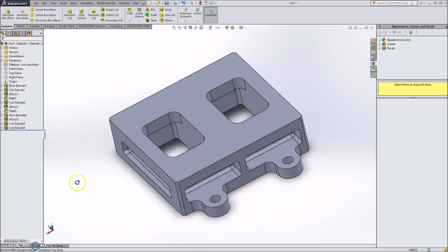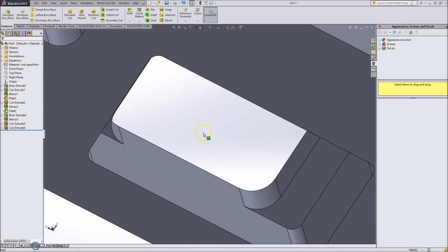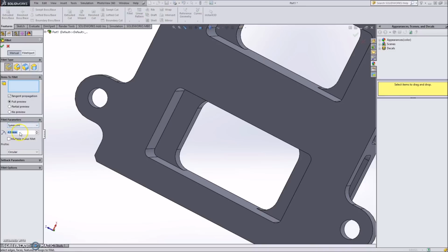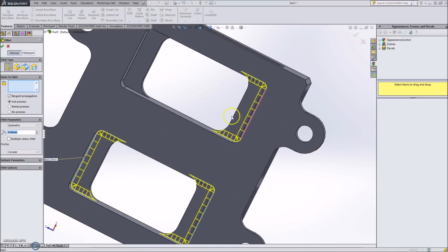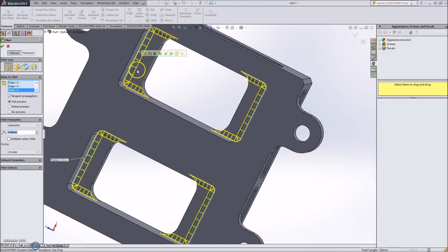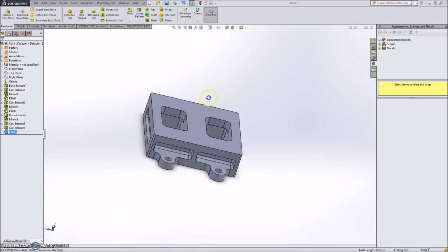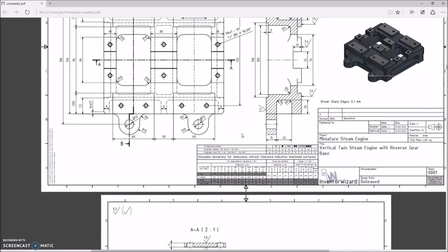That should get us those shallower extrusions, and that looks correct. One last thing that we need to do, there are also fillets of radius 4 on the underside in these sections as well as shown in the drawing, so we will apply those manually real quick. Alright, now we have our center holes for the part.